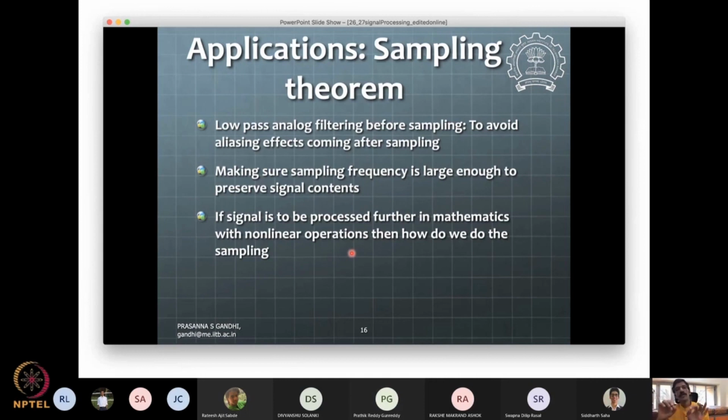So the idea here is to use an analog domain filter first. You don't get directly into sampling a given signal. Given a signal, you know what frequency content is of interest to you, and use that as the cutoff for your RC circuit, and use that circuit on board before the signal is taken into your microcontroller.